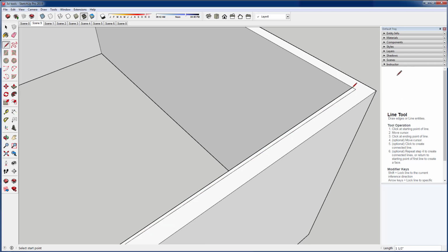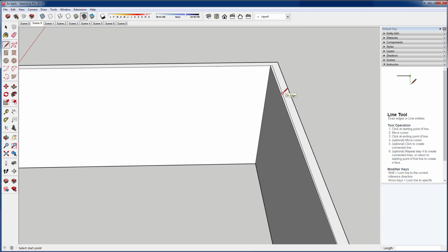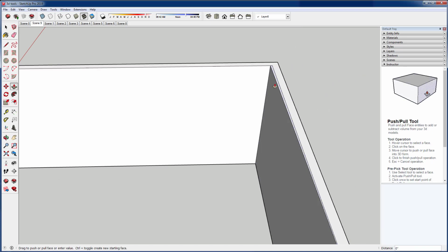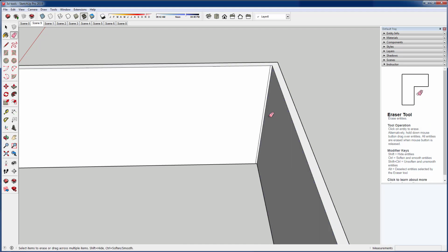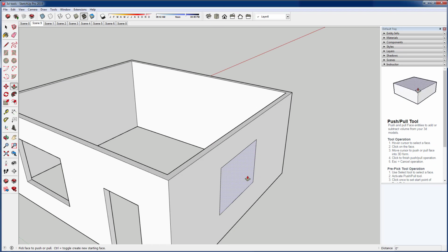and then I can just come over and touch it to the corner and pull that up to there, and then I can see how much my wall is out of alignment. By clicking and dragging this down to the bottom edge, it repairs it, and I can erase that little extra line there. And now when I go to punch that hole, it'll work.